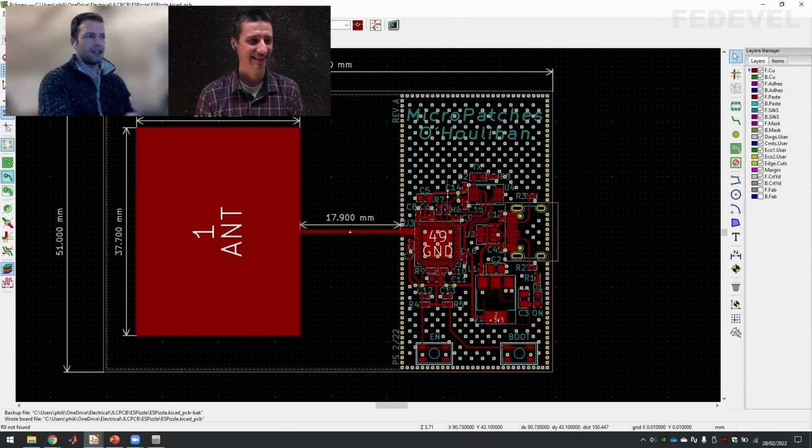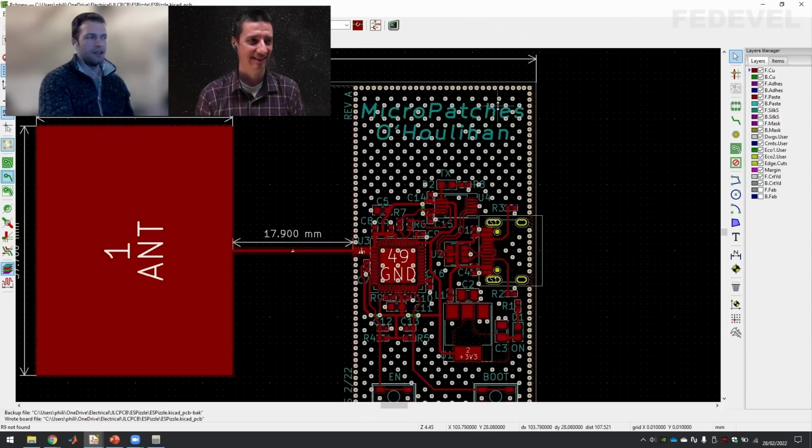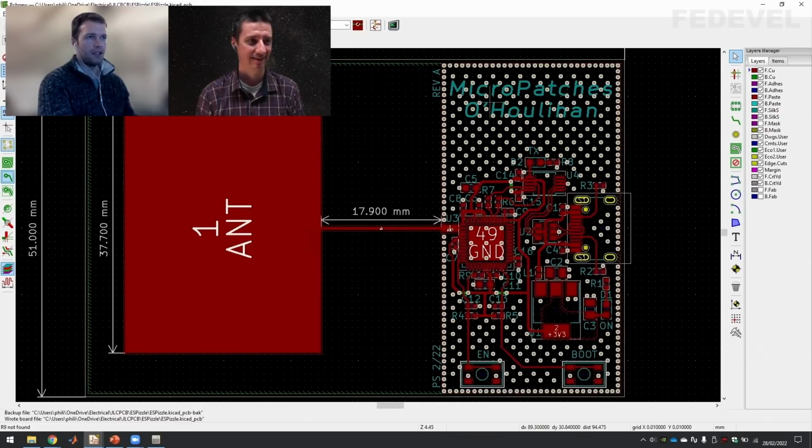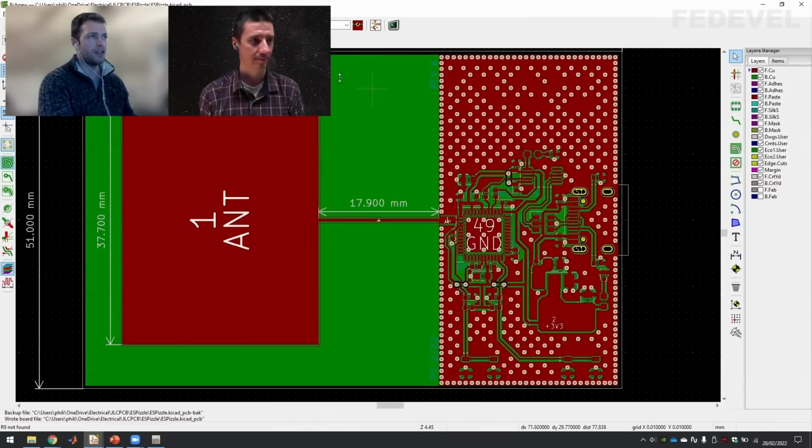Yeah, with the PCB design, there's nothing special about it. To have via stitching, because in this part on the right here, you see all these vias. I have a ground plane on the top as well. I voided all of the ground plane on the top layer around here because, of course, that will change the impedance. It will change the resonant frequency. You want this area clear of solder mask pretty much. But there is still a ground plane on the bottom. I think I can show this here. So like this, green is the ground on the bottom, and red is the copper on the top.